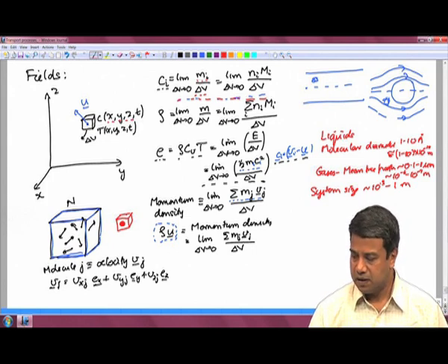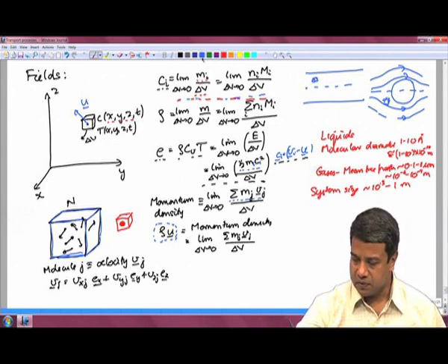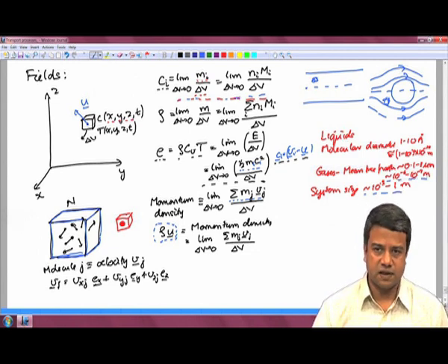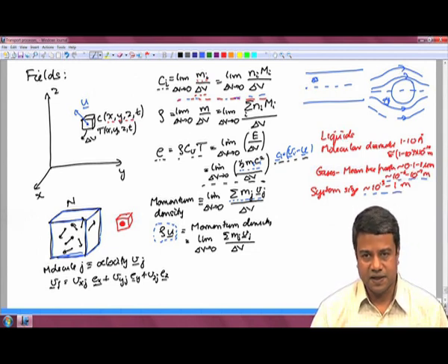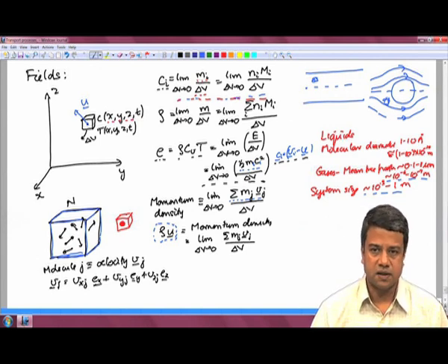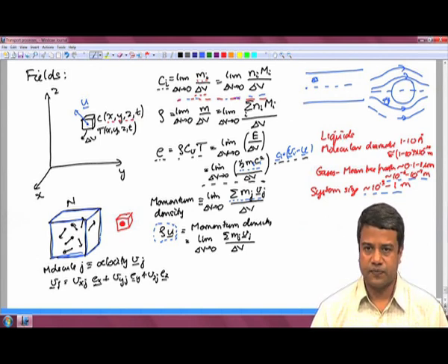And you can see that between these two, there is a sufficiently large range of length scales that it makes sense to define an intermediate scale that is approximately the geometric average of these two, in such a way that we can define a volume that is small compared to the macroscopic scale, but still very large compared to the molecular scales. And it is in this intermediate regime that the continuum approximation is valid.